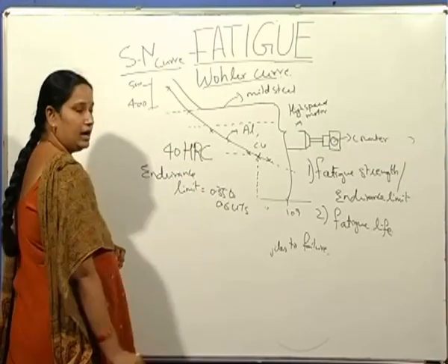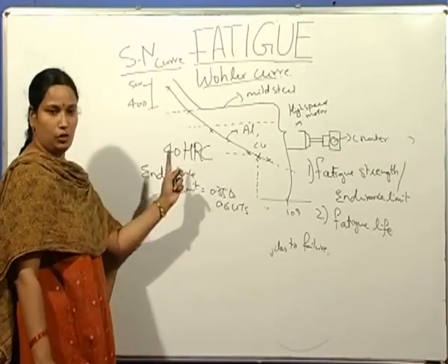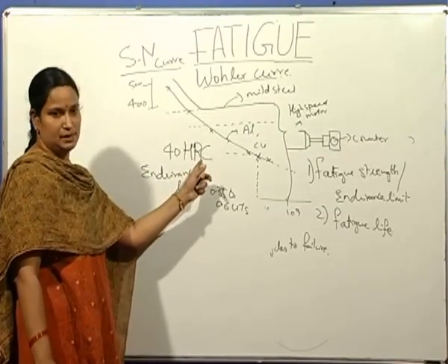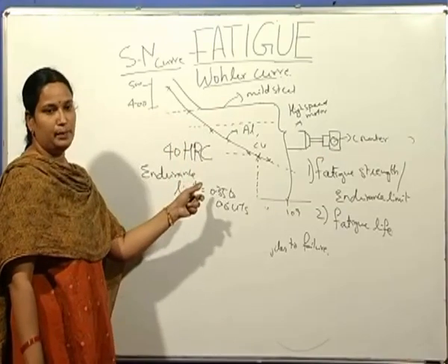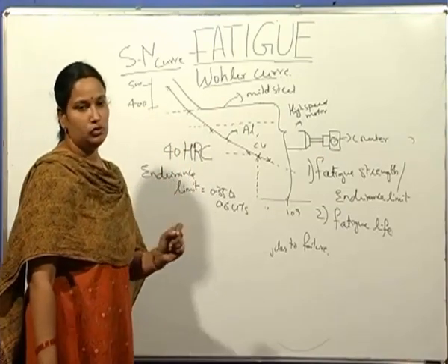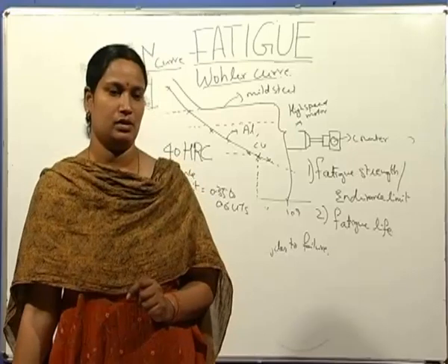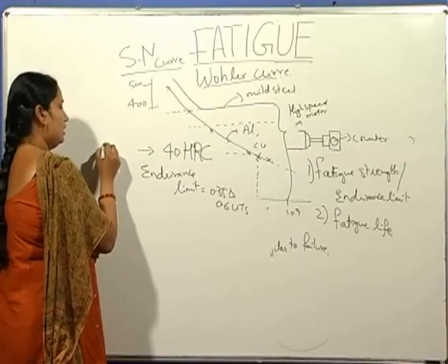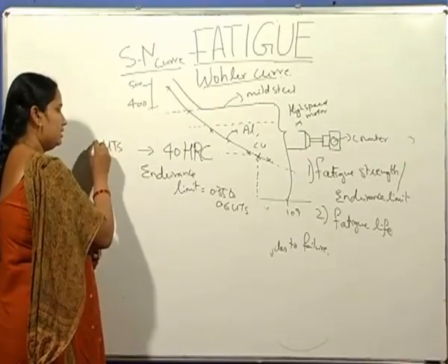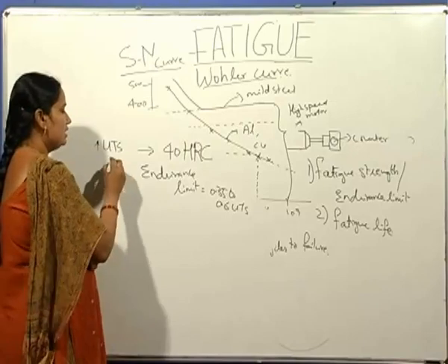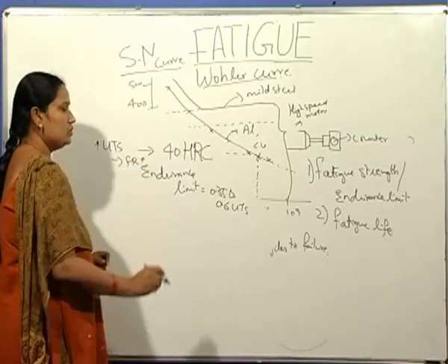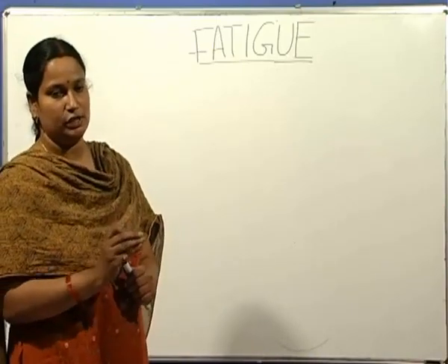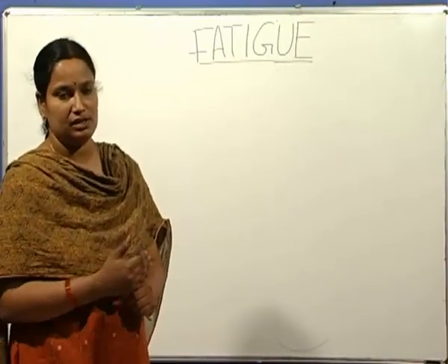Already we have discussed hardness. HRC is Rockwell hardness when tested using the C scale. C scale is a combination of a diamond cone indenter and a load of about 150 kg force. So up to this particular value of hardness, it has been found that as ultimate tensile strength is higher for the materials, the fatigue resistance is also higher. Generally, fatigue crack initiation takes place at the free surface, at the external surfaces.